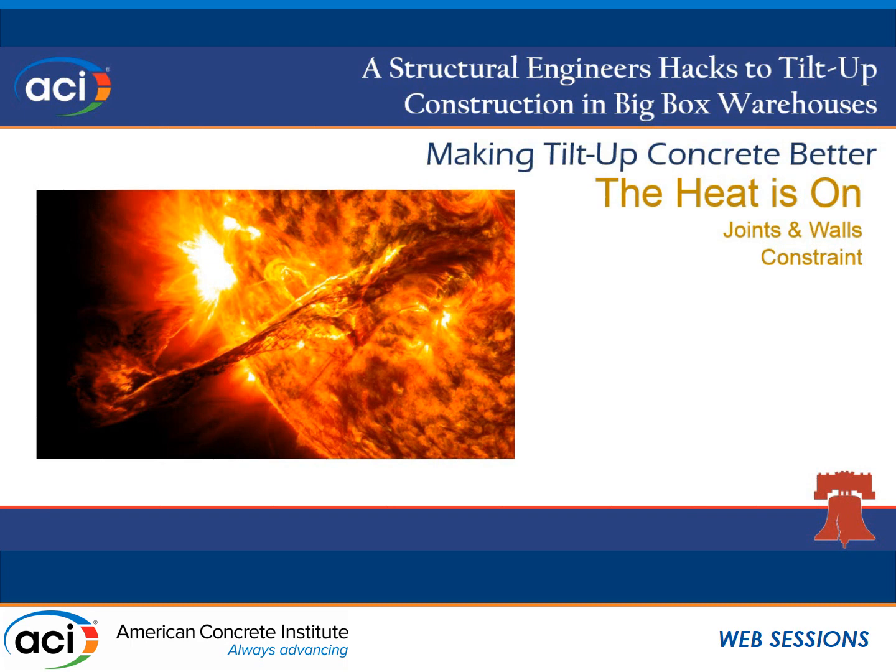So no matter what your thermal load actually is, trying to carry that expansion joint through the wall, it's just not going to move. It doesn't matter what your thermal load is. So I don't carry my expansion joints through the wall. Plus, it's a hell of a thing to try and caulk a 2-inch joint. Contractors love that.